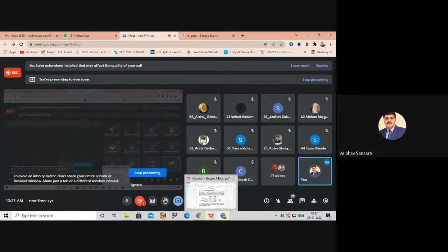So this discriminator gives the feedback signal to the input translator and digital comparator, and accordingly the position of that rotor will be finalized for the second step. So after completion of the first step, the second step is initialized in the closed loop control of a stepper motor, because for second step initialization we require the actual rotor position after the first step of excitation.